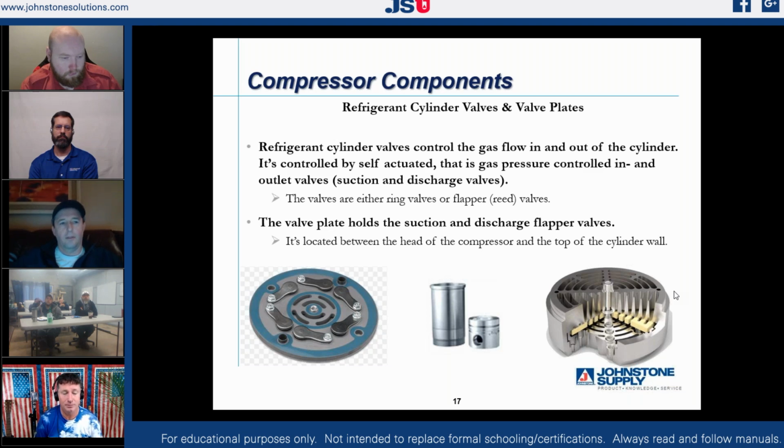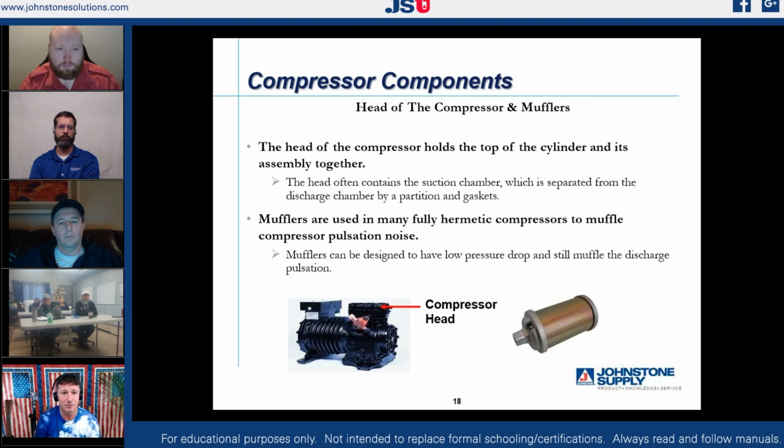I'm not producing my compression ratio in my vapor pump. So there's different styles. There's pop-up valves, there's reed valves, and depending on the manufacturer of the compressor, there's a variety of different applications, but they are all mechanically operated valve assemblies. Sometimes we do add mufflers to a system. The head of the compressor holds the top of the cylinder together. It often contains a suction chamber, which is separated from the discharge chamber, and a lot of times we'll use mufflers to aid in that pulsating sound.